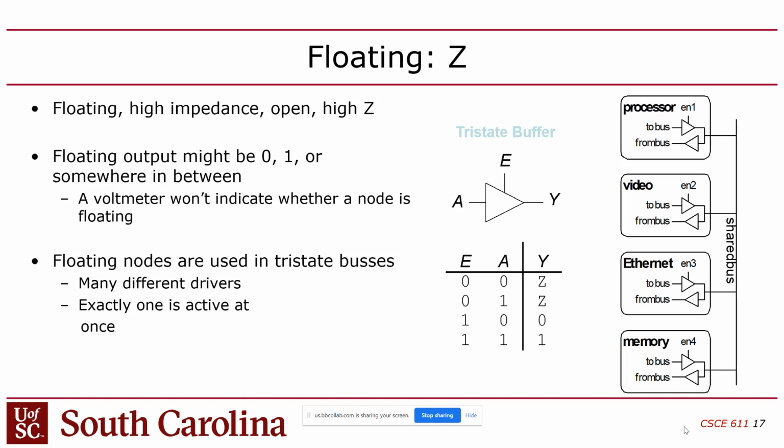You called it Y temp in this part, and you called it Y2 in this part of your code, and you meant for them to be the same, and they weren't. They have different names, and thus they're disconnected. All the connections are done through names inside of a module. So the wires are, like I said, a name, similar to the way SPICE does it, if you remember that from your electrical class.